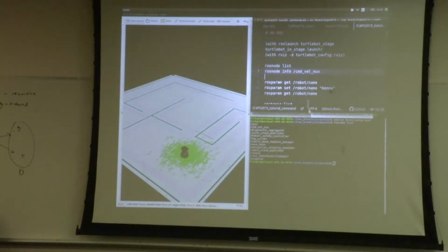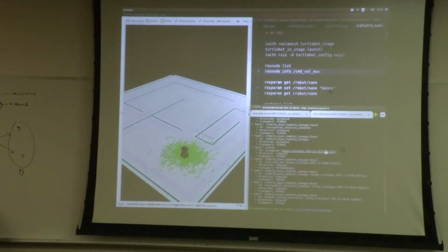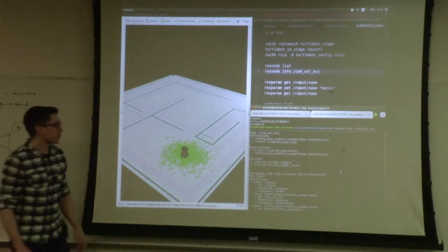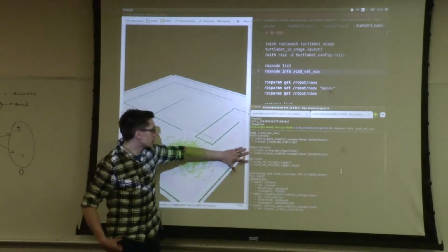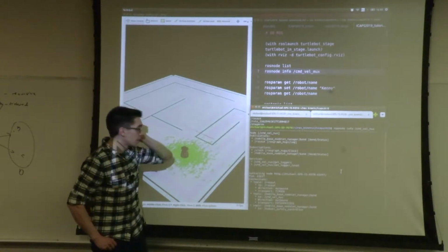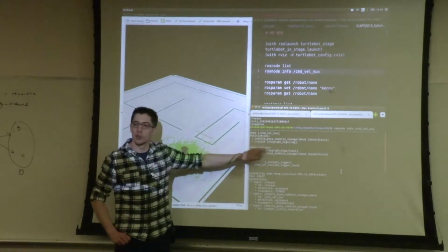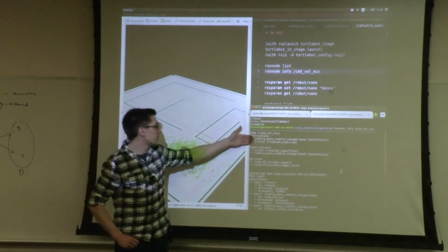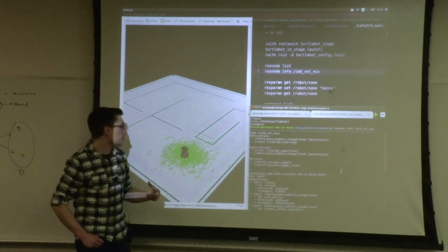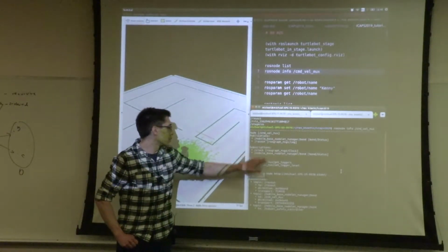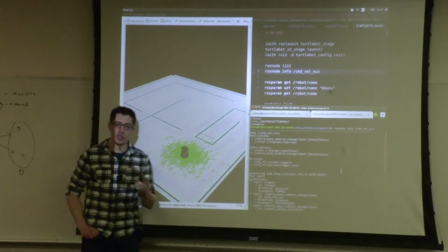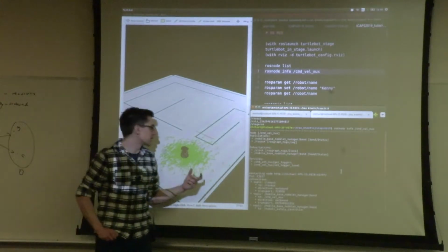To see that one in a bit more detail, you can do rosnode info. And this tells you the name of the node, but also the subscriptions and services and publications that it provides. So all nodes publish to rosout, which is just the debug stream. This one is also publishing to the mobile base nodelet manager, so that's it publishing to actually move the robot. And it's also subscribed to that. Essentially there's only the navigation asking the robot to move, so the multiplexer is not really doing very much in this.